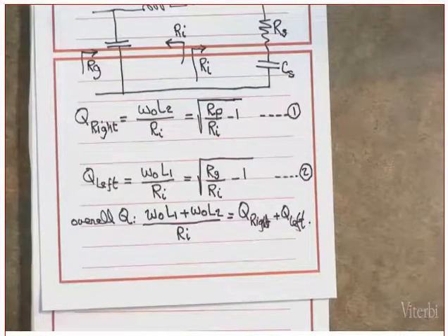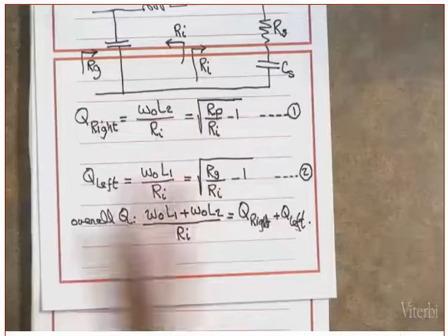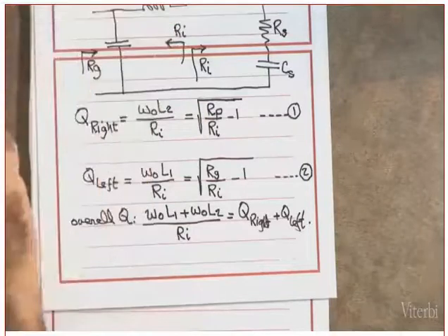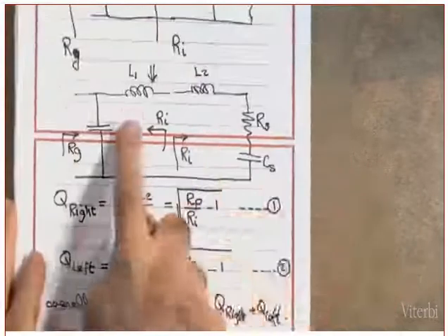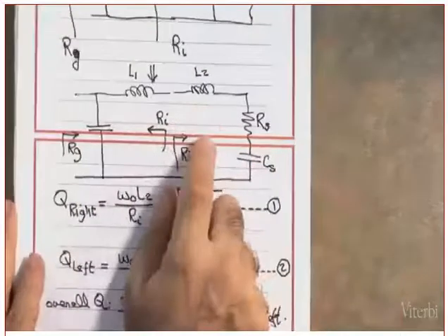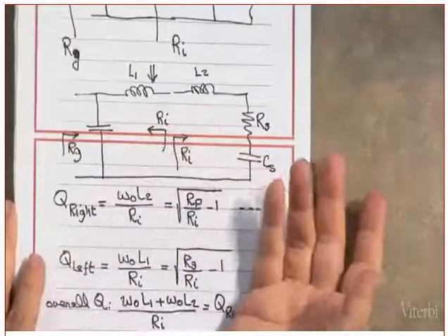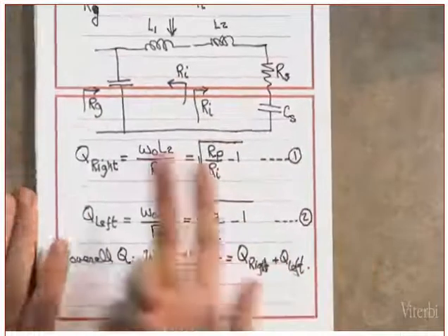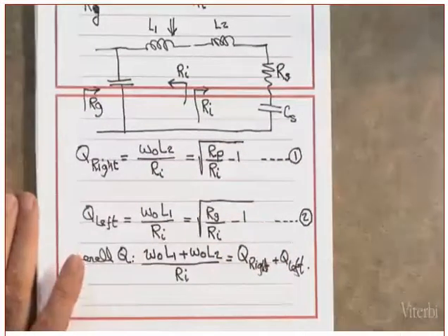You understand that or not? Different values of Q, different values of resonance frequency, and so on. So you don't want to be stuck with one equation that will decide everything. The only disadvantage is adding complexity. You are adding 2 L. So if they are going to provide for insertion losses, you are going to get double insertion losses. That's the price you pay.